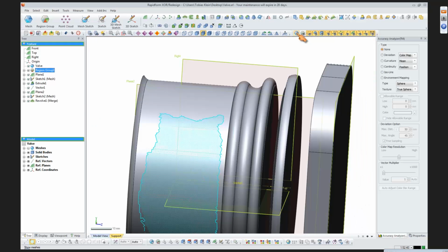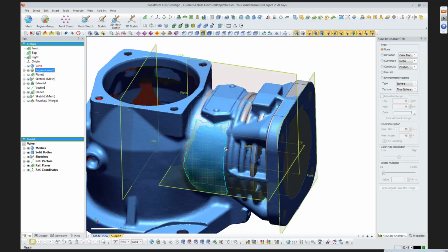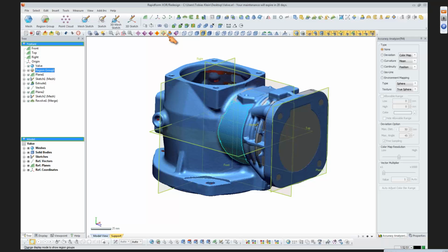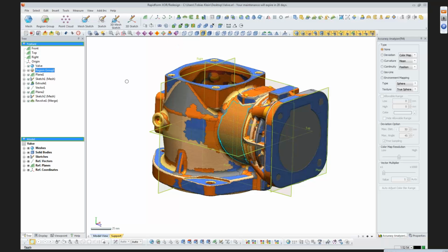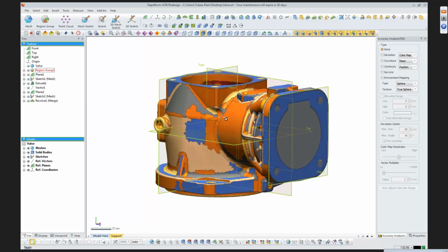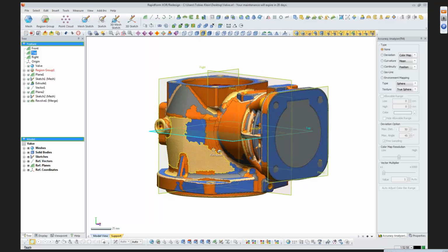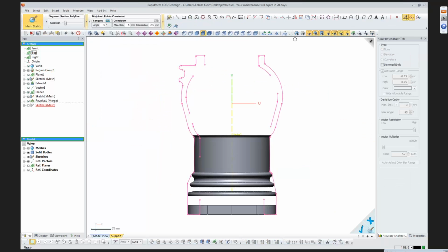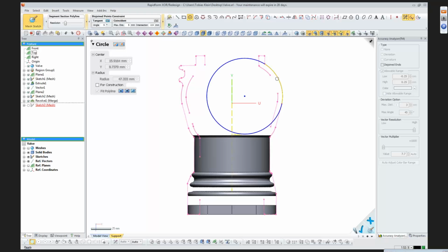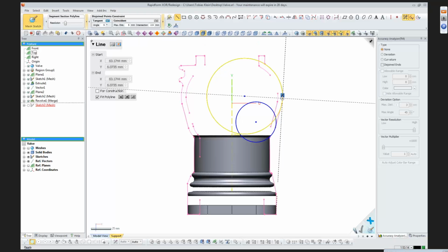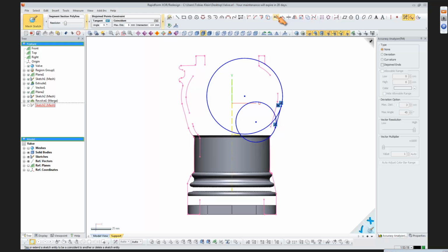That is extrusion and revolution, but it also works on sweeps and lofts. So we can have a look at one from here. Let's say I will create a profile here, and I will extrude that profile using a manual method. I'm just clicking here, combining this line tangent to this circle, deleting what I don't need in this inner area, creating a coincidence, creating a tangency.